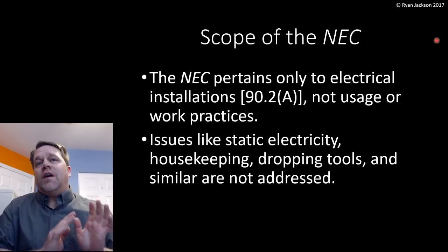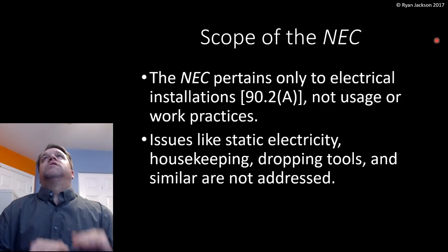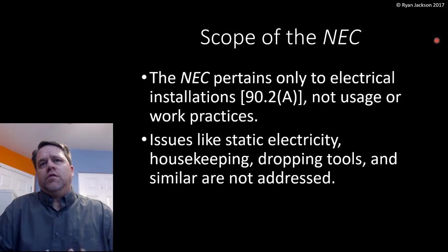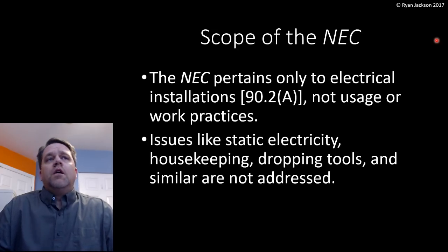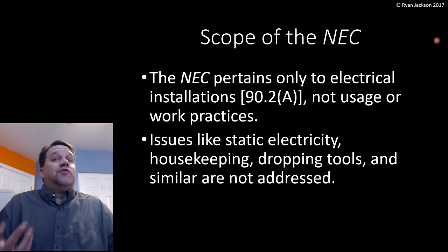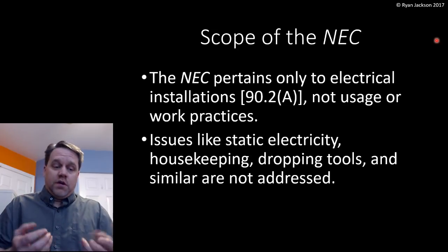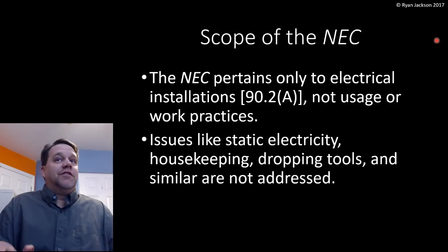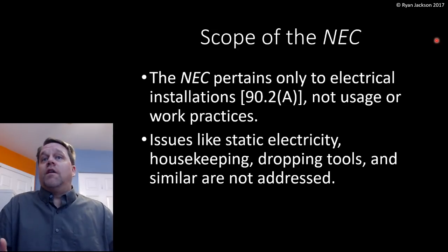It doesn't cover housekeeping, and housekeeping is essential in hazardous locations, especially in Class 2 locations, those locations that are hazardous due to the presence of combustible dust. Dropping tools. If you drop a metal tool on concrete, it can arc, right? And that's not a big deal in 99.9% of our lives.